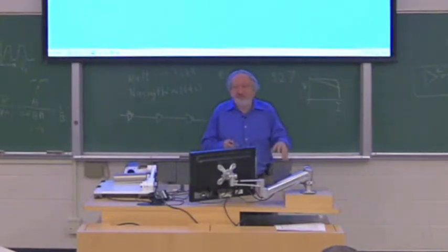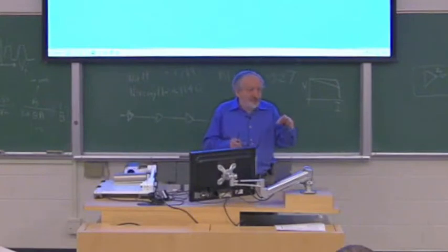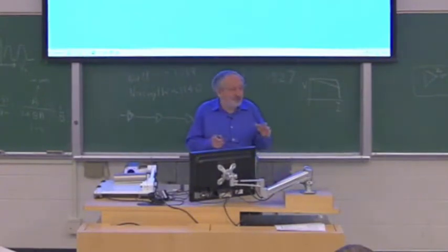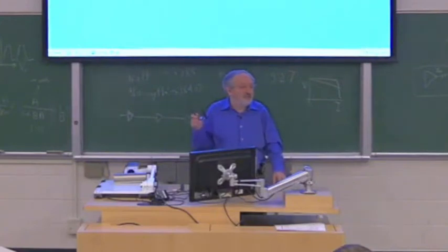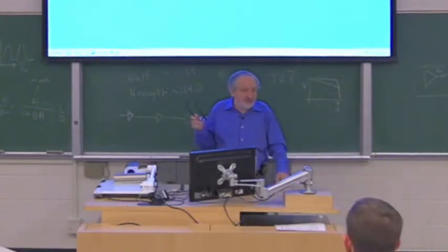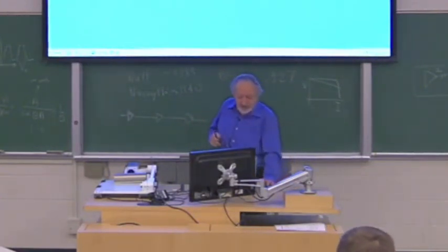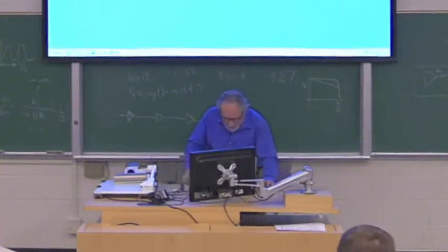Because oscillators in those days were just an LC circuit, coil and capacitor, but since the gain changed with frequency, when you change the frequency, the amplitude changed, and that was very annoying. So people wanted an oscillator that you can change the frequency, but the output stays constant, just like all oscillators today.